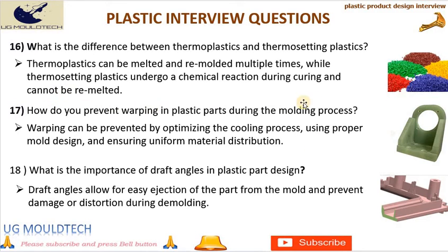Friends, next point in injection molding interview questions is 17. How do you prevent warping in plastic parts during the molding process? Warping can be prevented by optimizing the cooling process, using proper mold design, and ensuring uniform material distribution.